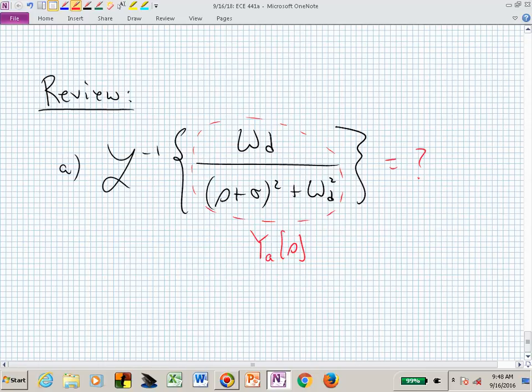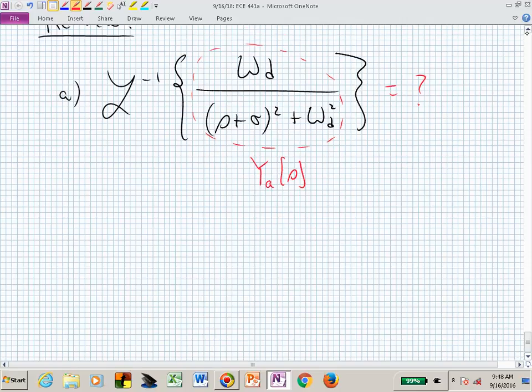Now you're going, okay, second order. Is this second order, first of all? Yes, it's s squared in the denominator. What could you do to buy time while you're thinking about what's going on here? What could you tell us about this? Can you say anything about the poles and zeros? Can you sketch the S-plane plot of poles and zeros? Can you put down X's and O's?